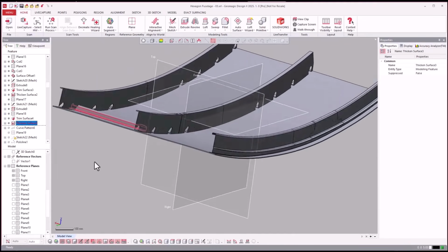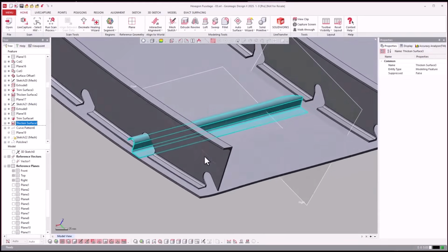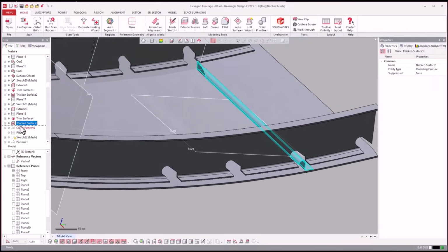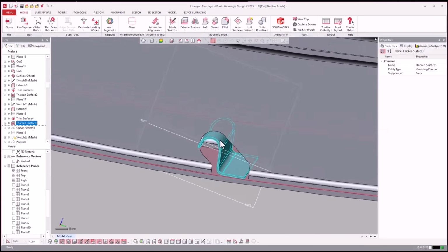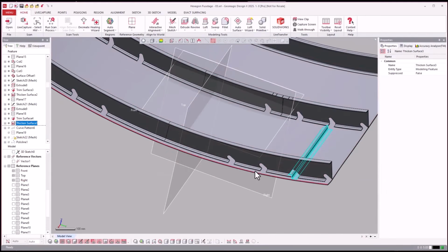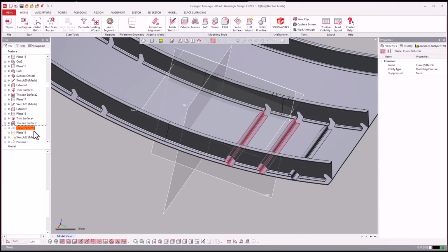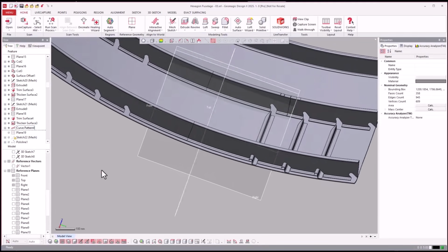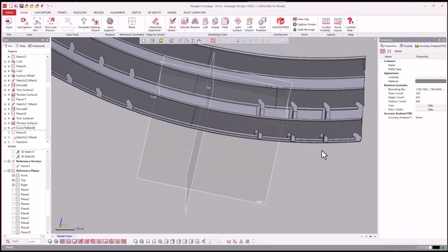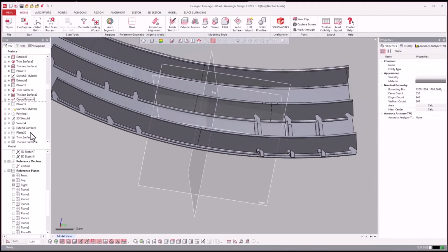What we did over here is we started modeling these brackets. We extruded it as a surface and thickened it. Again, this one's different from those other ones. I know because I fit it and tried to pattern it and was messing with it myself. Then you discover what works and what's not actually a pattern. You have to model it as a separate instance.